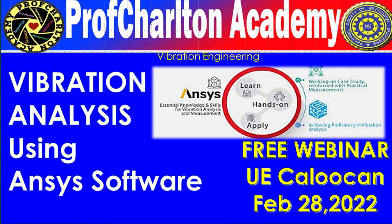You have to define the Young's modulus and the Poisson's ratio. These two are the basic properties needed to run the stress analysis. Without Young's modulus, we cannot calculate stresses. These are the material properties, which are basically user input.